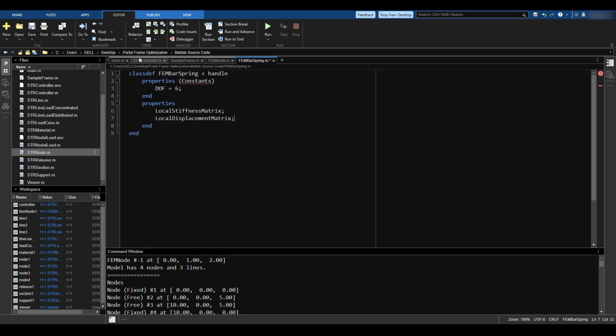This is the displacements of the nodes in the local axis sets. I would also need the local force matrix. I would need those two because I may be interested in finding the local forces of an element for post-processing purposes. Because you know that local forces equals local K multiplied by local displacement, X. So I need to have them, and I need to calculate them.